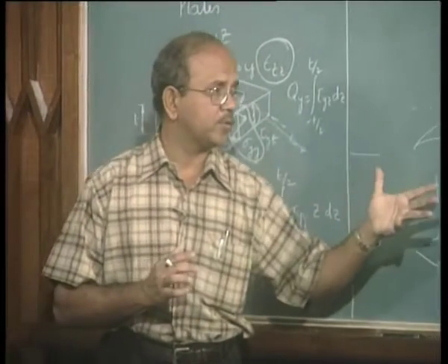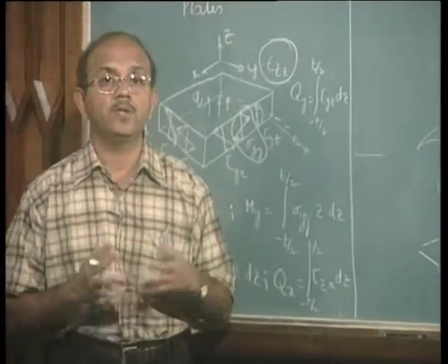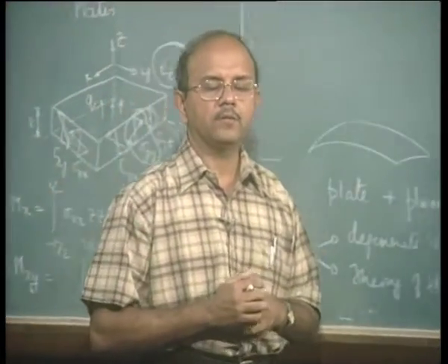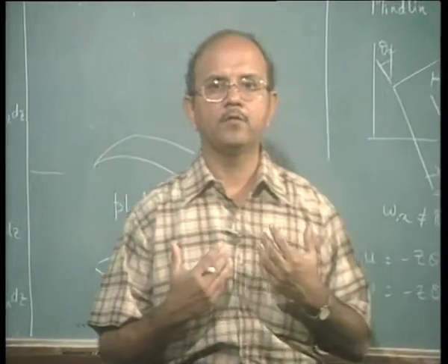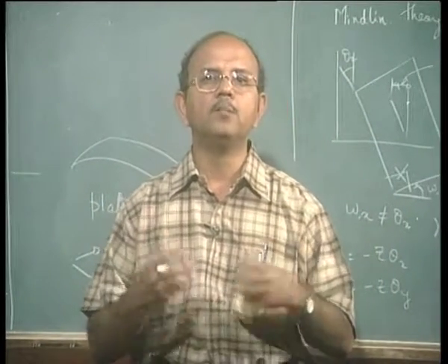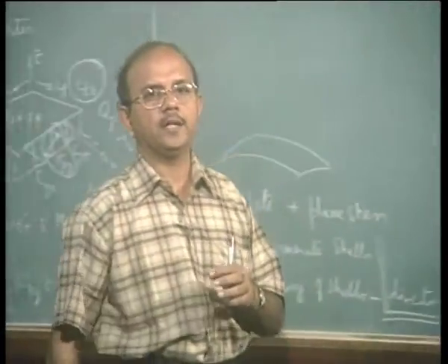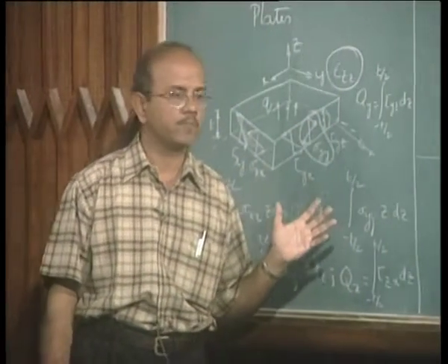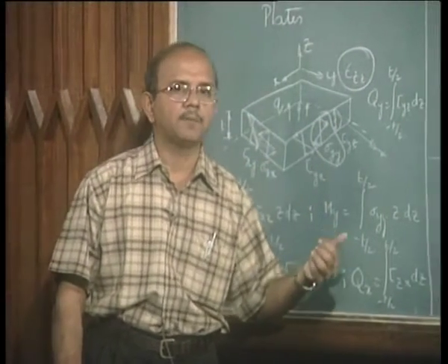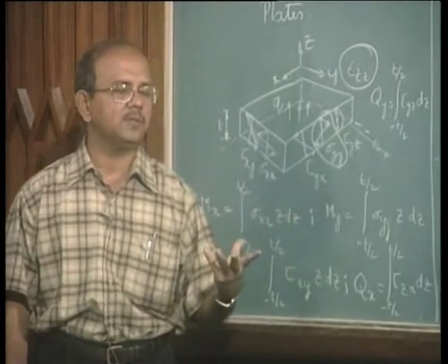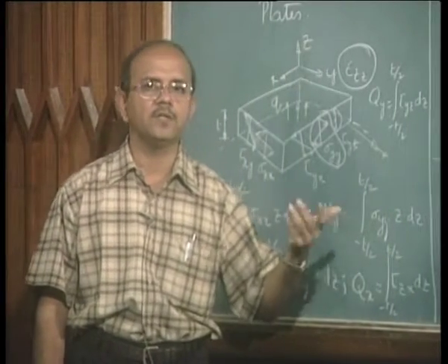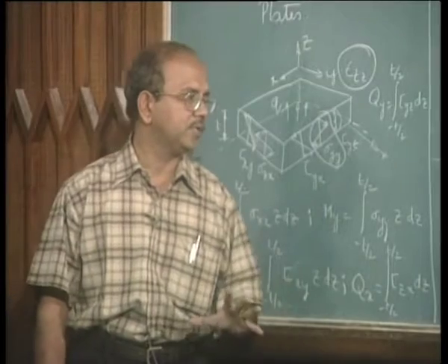There are a number of situations, for example, in sheet metal forming, where a door of a car has to be modeled. Then many times you use a shell element. Sometimes people use what is called a membrane element. Again, this is a modification of the shell element. We will not go into the details of it.